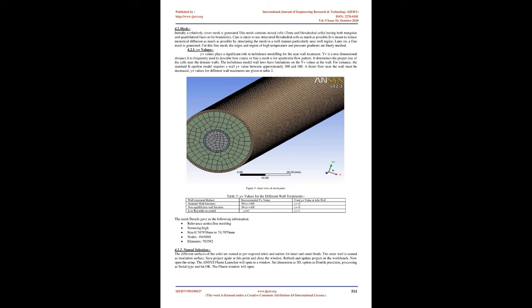The literature survey reveals that most of the analysis was done by considering constant heat flux or constant wall temperature boundary conditions. Literature regarding the numerical study of enhancement in the heat transfer characteristics using different configurations of internal longitudinal fins for a double pipe heat exchanger with conjugate heat transfer is still scarce. Hence the present work aimed at the comparison of heat transfer characteristics using different mass flow rates and temperatures for parallel and counter flow of a double pipe heat exchanger under various operating conditions to evolve the best possible configurations. Numerical simulation was done using a commercial CFD package.